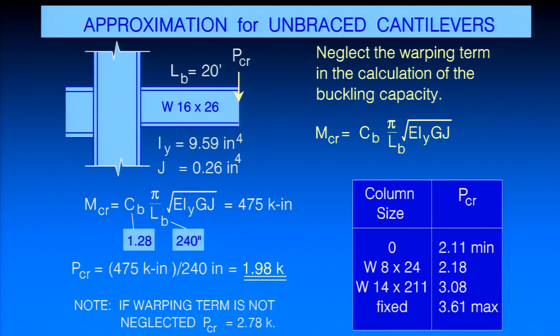Now alternatively, you could put continuity plates across the panel zone here, and that's going to really stiffen that up, but you're also going to have to take out your pocketbook and pay a lot of money. That's a really expensive detail. So a lot of times it's more economical just to say, I'm going to conservatively neglect all the warping stiffness and I'll have a conservative estimate there. But anyway, it's an approach you can take.